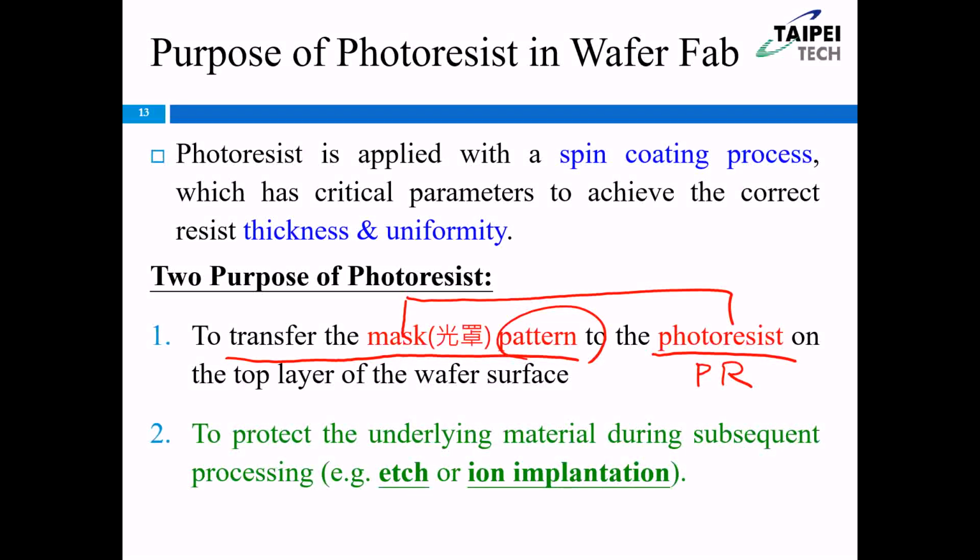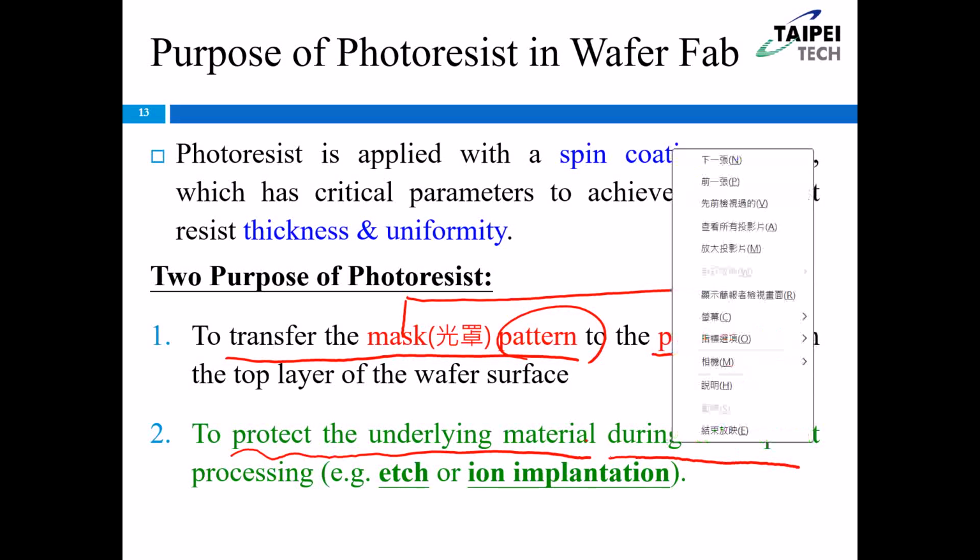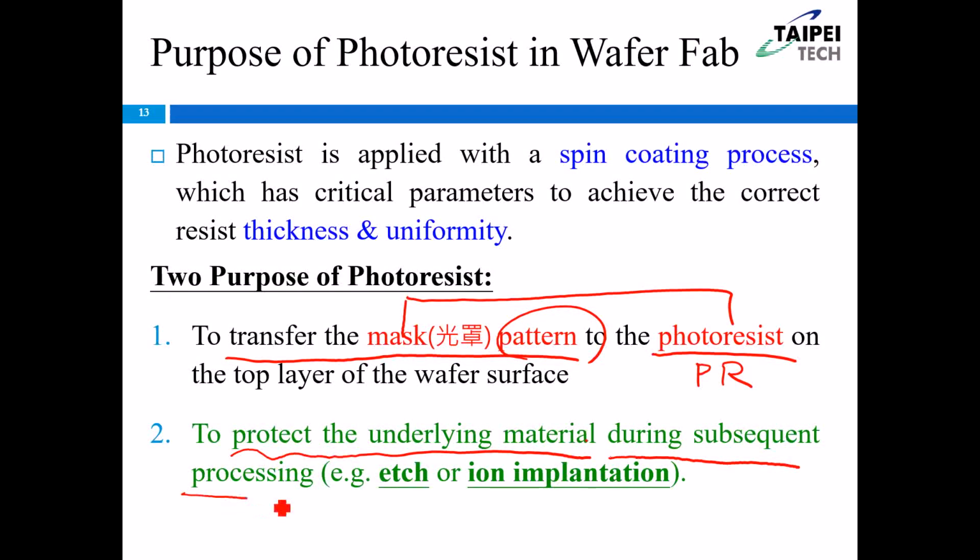And the second purpose, we want to protect the underlying material during the subsequent processing, like the etching or ion implantation.